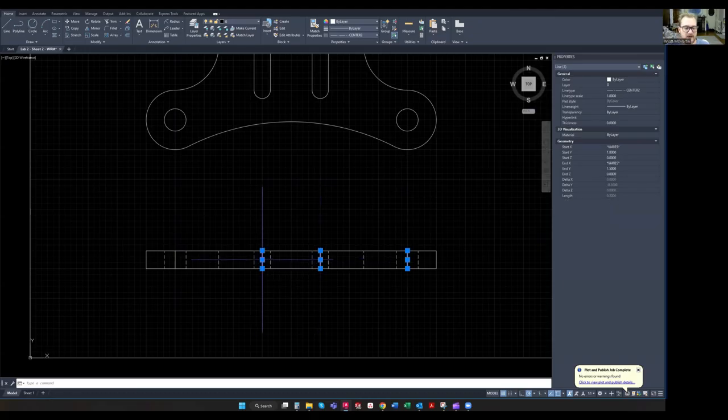You can do an LT scale of 0.25. That would change everything, but I like how the hidden lines look here. So let's just select our center lines, and then up in the local LT scale, which is still 1, because our global scale is at half scale. So our local scale would still be 1, and then it would be affected by the global. So you don't have to really worry about that right now. All you have to do is in this LT scale right here, type 0.5.